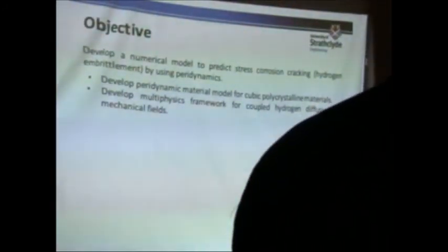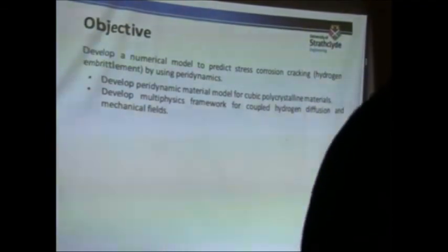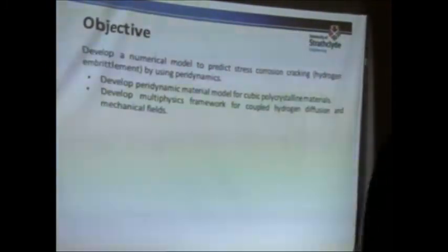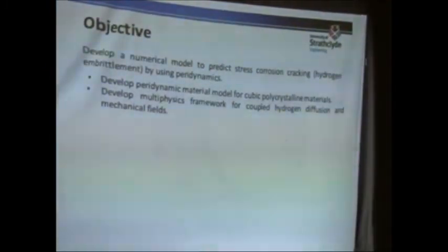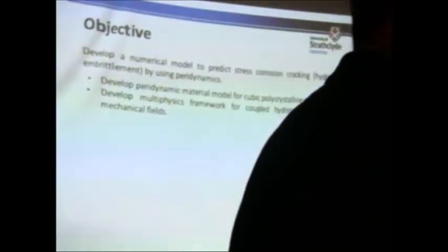After coming up with that particular material model, we also developed a multi-physics framework to couple the hydrogen diffusion field and the mechanical field, because there are multiple stress corrosion mechanisms, and the one that we are particularly interested in this study is hydrogen embrittlement.